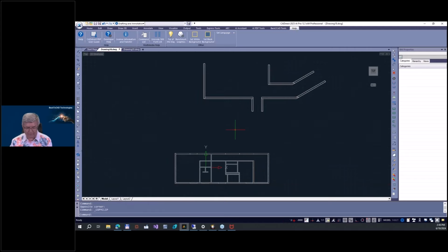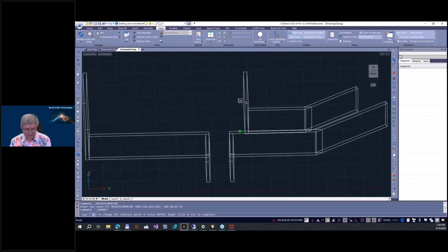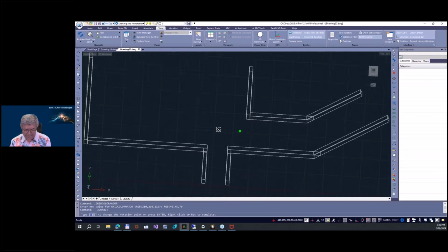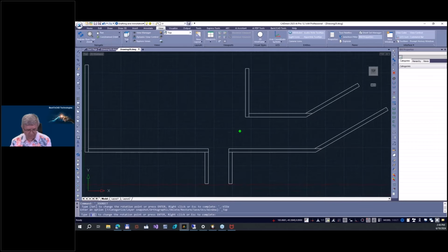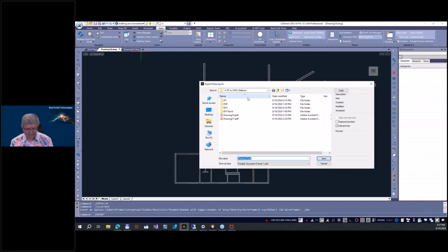Or what I told you, another possibility is if you need the walls 2D, because this is everything 3D. Okay. If you go here on View, Constraint Orbit, you can try now here to make this flat, but I show you something. This is the flatten. Okay, so you can flatten, but I show you what is the problem with this flatten. But what you can do, if you need this two-dimensional, okay, is go here on export as